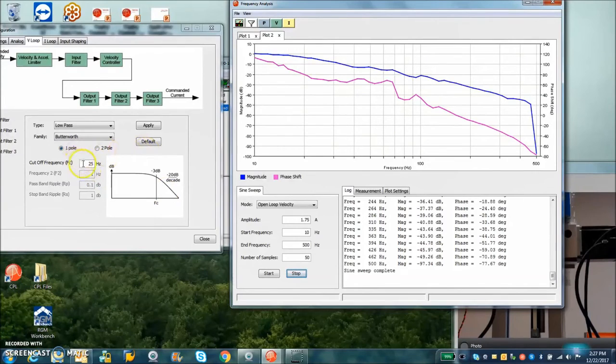So I'm trying a pole at 25 hertz. I got rid of the notch, and if we look at the phase shifting from 180 down to 0, and then look up at the gain, we're down to minus 30 decibels. So lots of gain margin, lots of phase margin. And we go off pretty flat and roll off heavily here, but the resonance around 50 hertz, it's a lot of mechanical stuff going on here, so there's a little funny business.